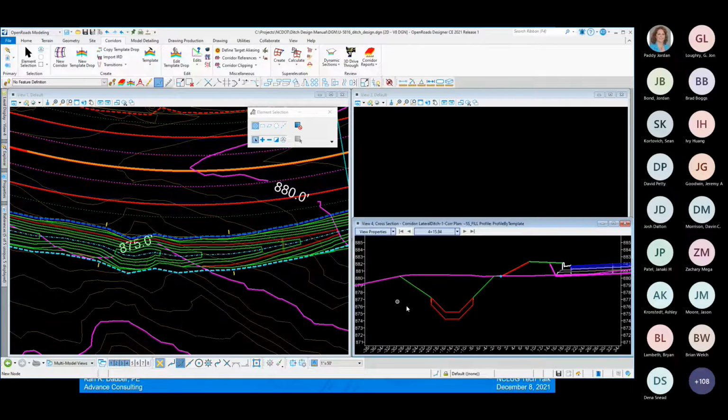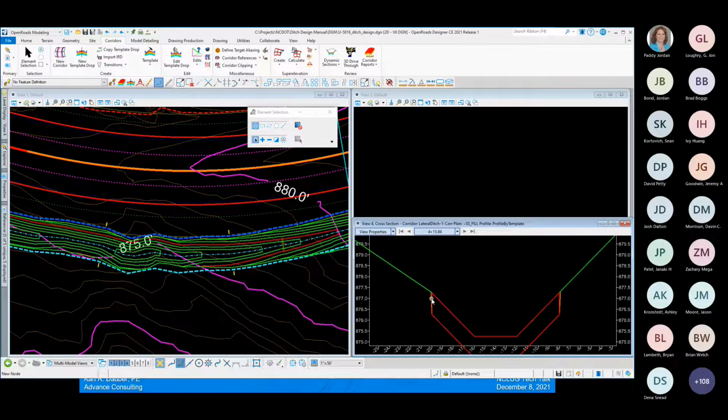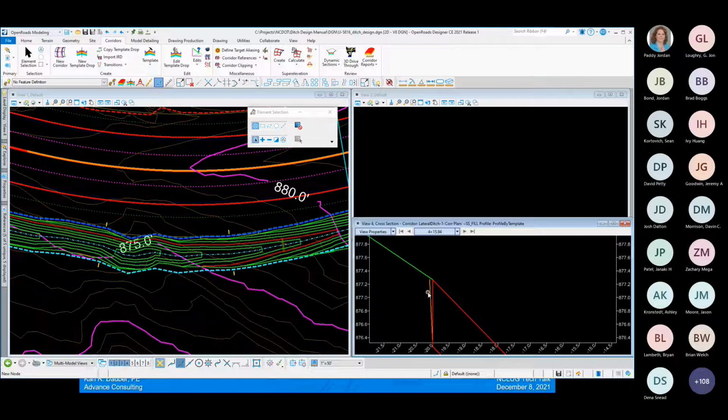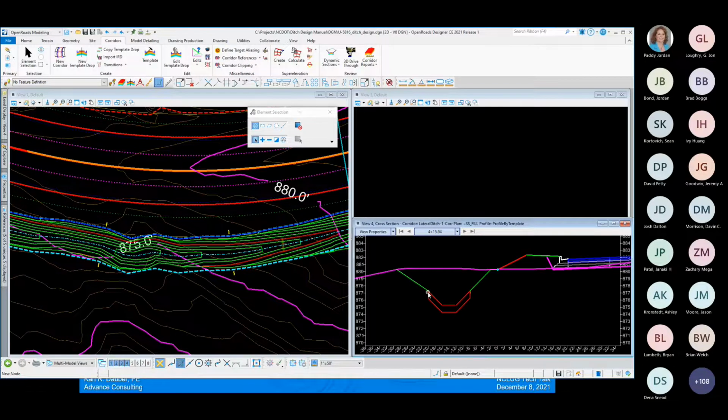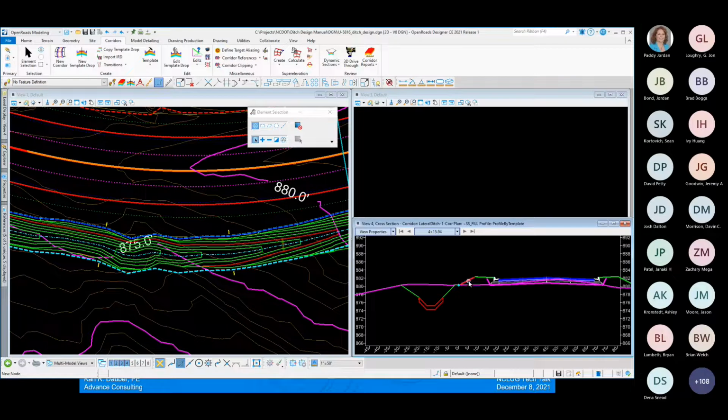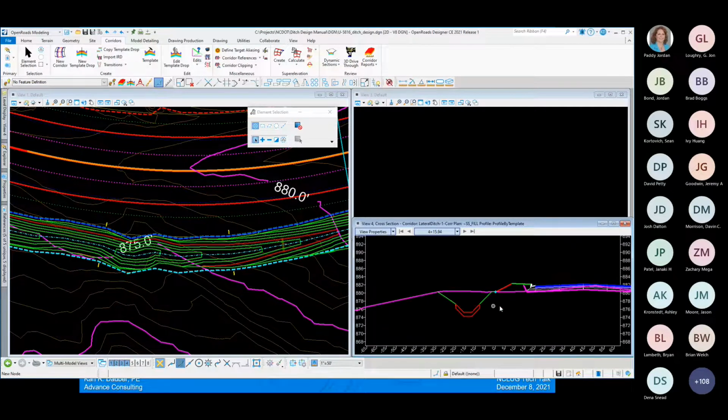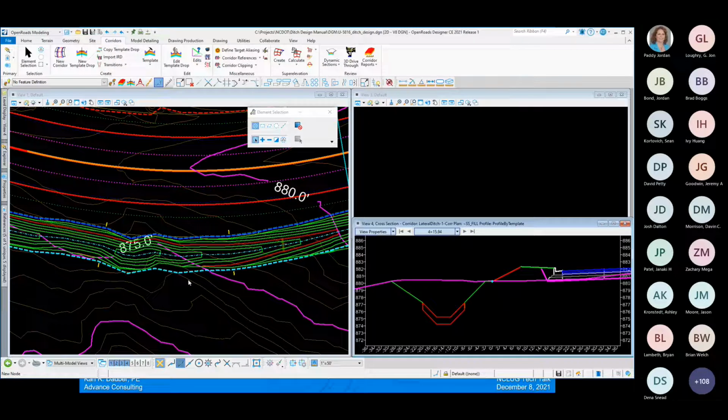And you can see that that shows all the elements of the ditch, including the riprap layer, as well as, if you zoom in, there's a geotextile fabric in there. Shows you existing ground, as well as the roadway corridor model and all the data associated with that. Any 3D data that you have referenced up will show up here. So if you have a drainage and utilities model that's referenced, your drainage will show up here. Any proposed and existing utilities, anything that's 3D will be reflected here.